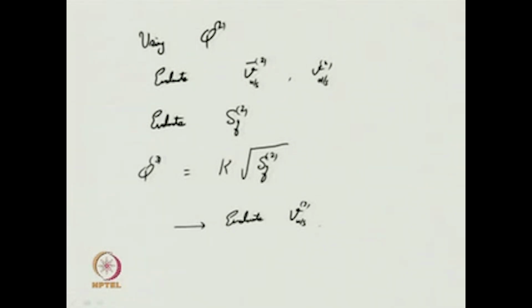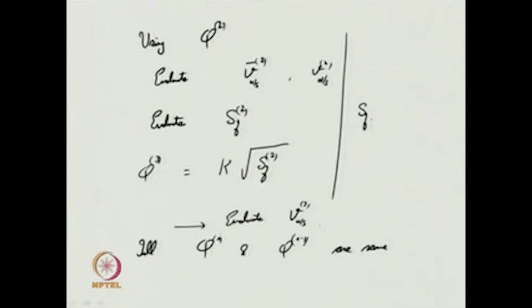So, evaluate like this till Q in the ith approximation and Q in the i minus 1th approximation are the same. Once you get this, the corresponding values of SF, V upstream and V downstream have to be noted, and now you have got the flood discharge.